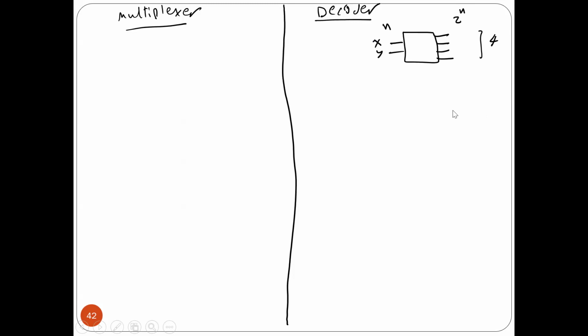So this is pin number 0. That means when the input is number 0, this pin has to be 1, and all the other pins should be 0. You got what I'm saying? So always one output is 1, and the other outputs are 0. That's how it works. So if the input is 0, this is the one that has to be 1. A 1 here means, as I explained last time, that it is active, and active can be 1 or 0, but here I'm teaching it assuming active high.